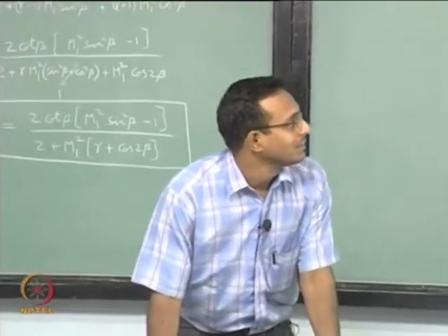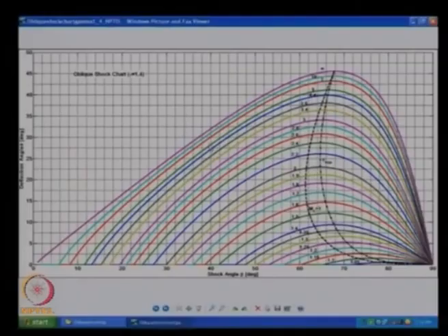So what we are seeing here is shock angle beta going from 0 degrees to 90 degrees and the deflection angle theta in degrees again. Okay. I am plotting it for oblique shock gamma equal to 1.4. Of course, I could get the whole plot for some other gamma value, we are using this because it is the most common thing. The plot looks like this, it seems like for every deflection angle there is double value for any given Mach number.